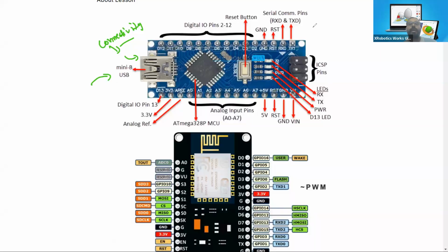But if we have to accommodate Bluetooth connectivity or a GSM module or something like that, then we have to utilize the TX and RX pins to provide the data coming from the sensor itself. Suppose we integrate a Bluetooth module to give the board a connectivity option, then we must connect the Bluetooth module to the TX pin and the RX pin for the communication.